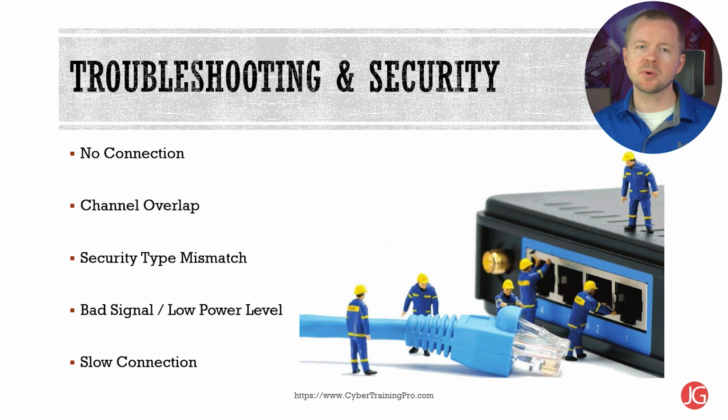If you're looking at the signal strength, the effective radiated power, or the ERP, is the signal strength coming from the antenna, which on non-directional antennas, the signal in any direction will be the same. The effective isotropic radiated power, EIRP, can be used to measure the relative signal strength coming out of a directional antenna to compare the strongest signal with an omnidirectional antenna. You might also want to look at your antenna placement.